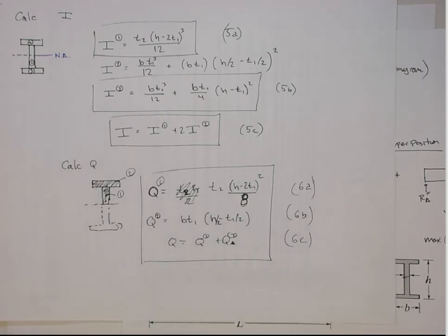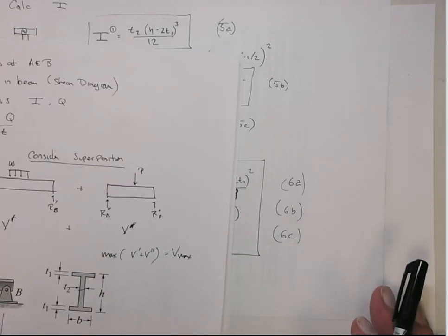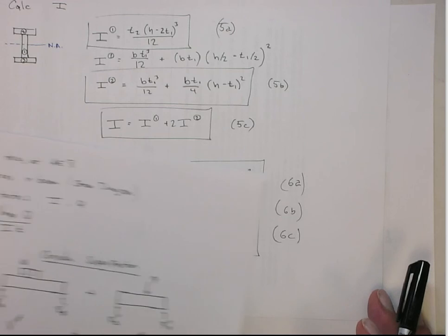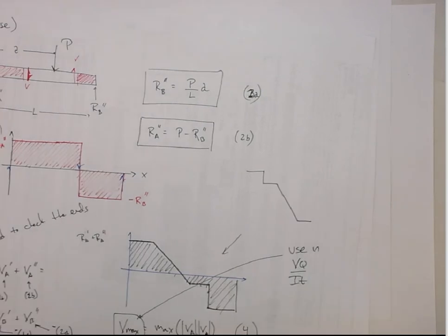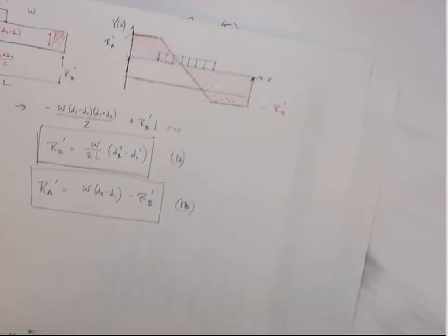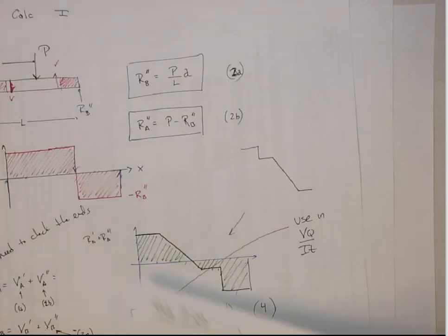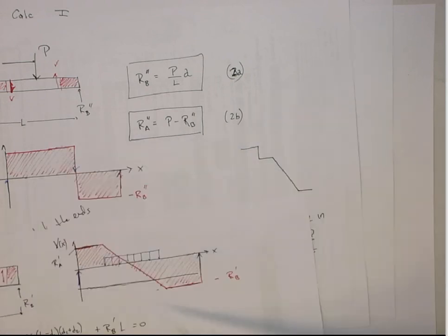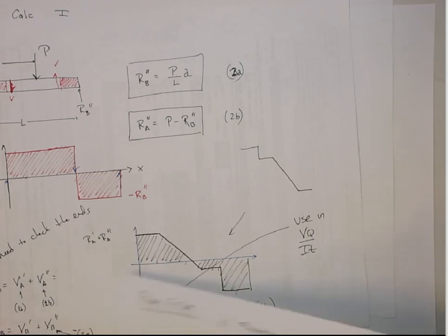All right. So where do we stand? Are we done? Well, I think we are, basically. We have everything to do the program. So first, we're going to compute the reaction forces for the point load and the distributed load. Knowing those, we can get the shear diagrams for both of those. We figure out the maximum shear. It's going to be at one of the ends.